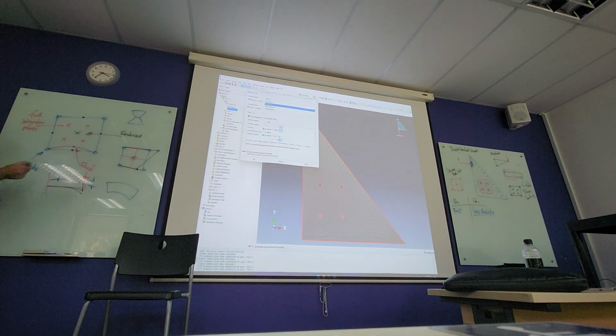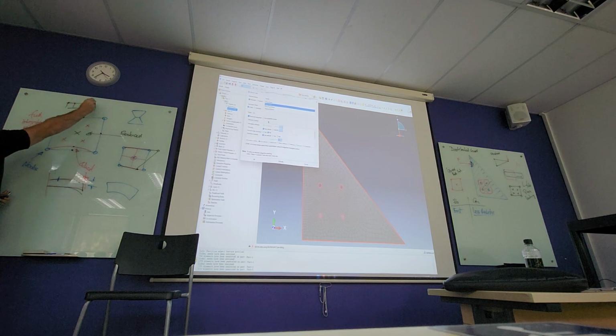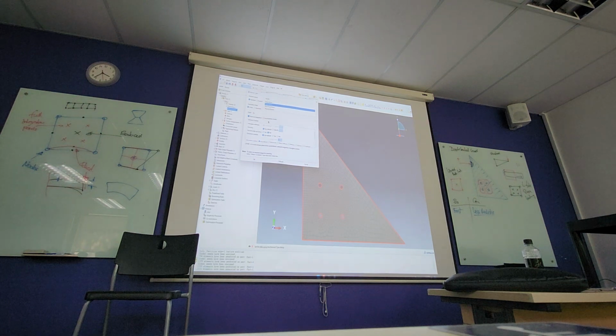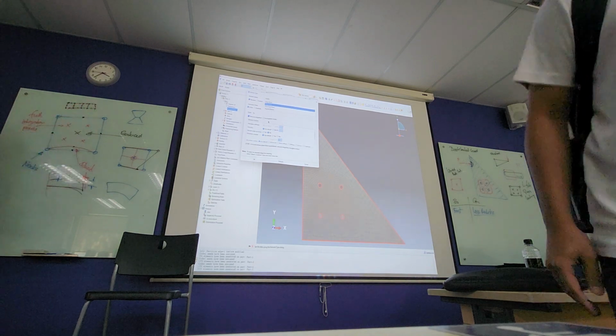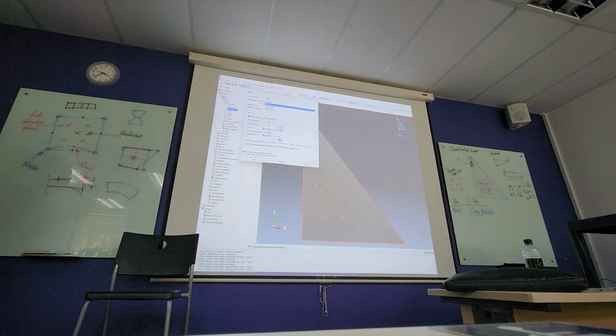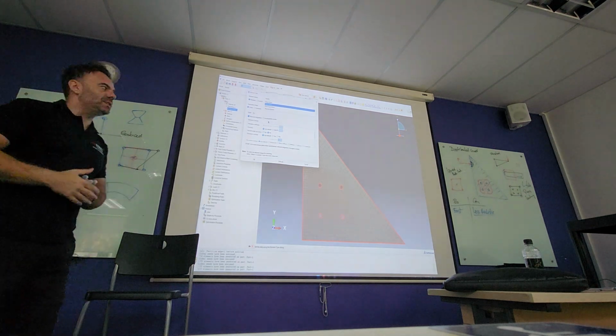So if you use, let's say, what is that for? So it'll be 1, 2, 3, 4, 5, 6, 7, 8, 9, 10. There'll be 10 nodes for those 4 elements, but if you switch it to quadratic, all of a sudden that goes up by that many extra. So you will exhaust your license. That's basically where the cost is.